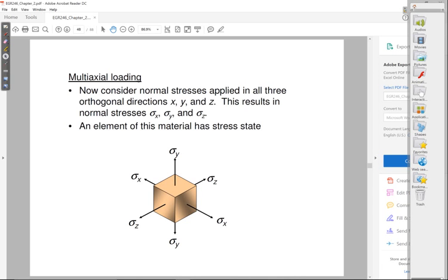We're going to apply superpositioning in this case as well, except that we don't look at types of forces. We're going to look at the individual stresses, meaning we're going to look at sigma x and look at what effect it has. Then we look at sigma y, then look at sigma z, and then we add up the effects of all 3 stresses to get the net effect.